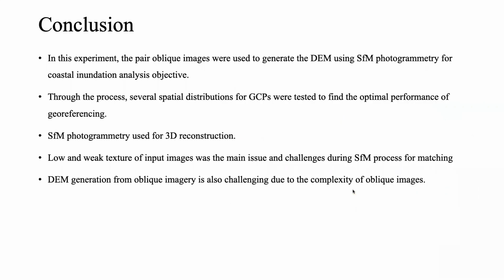As a conclusion, I can say in this experiment, the pair of oblique images were used to generate the DEM using SFM photogrammetry for the coastal inundation analysis objective. Through the process, several spatial distributions for GCPs were tested to find the optimal performance of georeferencing, and SFM photogrammetry was used for 3D reconstruction.